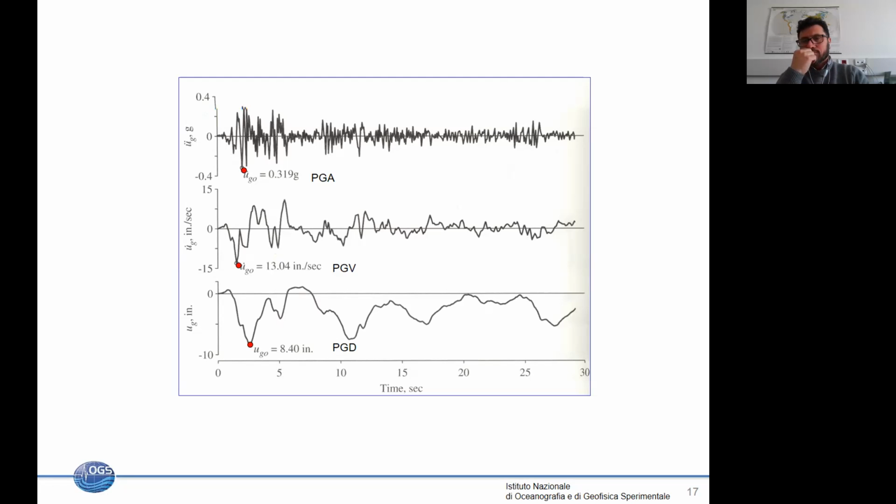No idea? So generally, if we assume a very simple shape of the earthquake spectrum, and we look at the displacement, we can imagine that the earthquake spectrum has a shape like this. For the low frequencies it is nearly flat, then above what is called the corner frequency, some of you, I think, heard it from Fabio Romanelli, I'm sure, the high frequency spectrum is decaying.